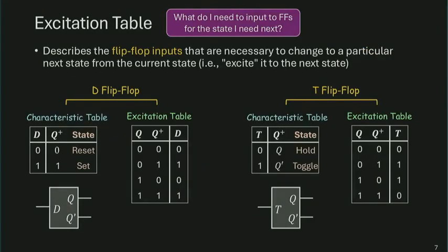All right. So now, with those 2 small examples out of our way, we're giving the implementation process a more formal treatment. Formally, how do we implement the next state logic for any given flip-flop? To implement a sequential description, we need the excitation table of a flip-flop. The excitation table is almost like the inverse of a characteristic table. The characteristic table describes how the flip-flop operates according to the flip-flop inputs. The excitation table describes what you need at the flip-flop inputs to realize a particular transition.